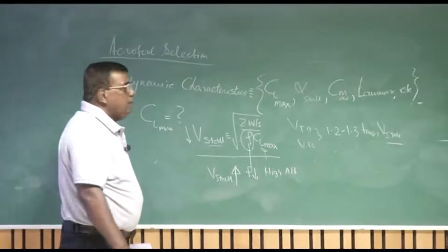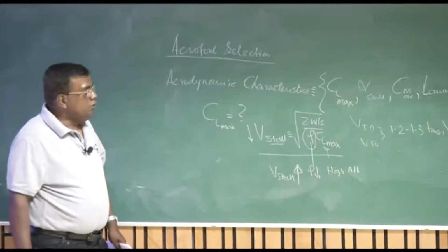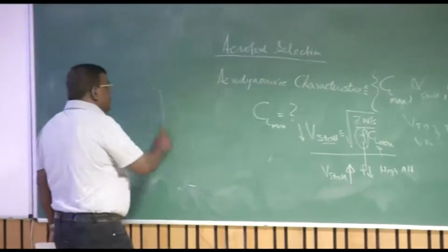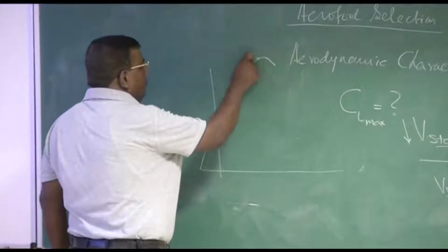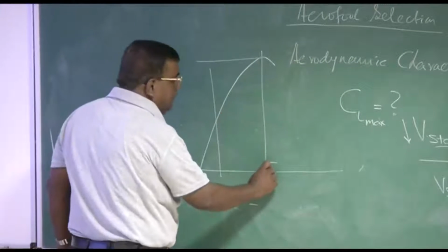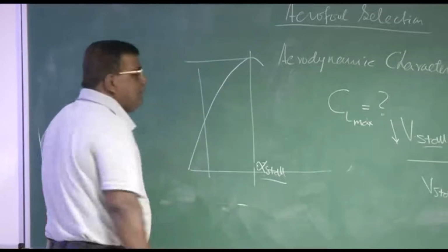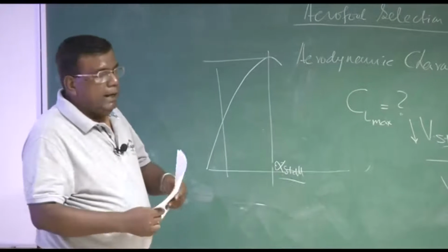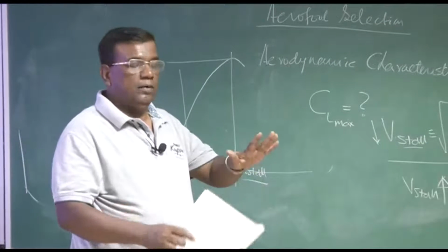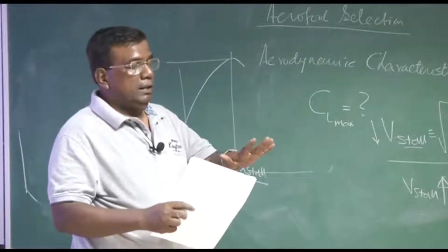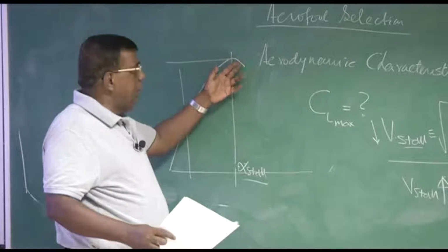Please understand, for an aircraft, takeoff and landing is very, very crucial. Let us say I am flying at CLmax, which theoretically means you are close to alpha stall. So imagine I'm coming for landing, and because of some ground effect or ground upward wind, the local angle of attack suddenly increases. Then you are actually falling here.